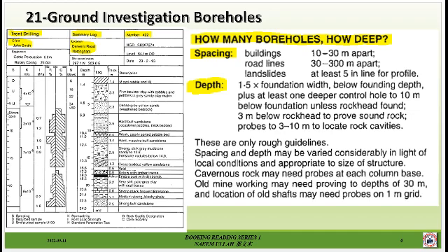Cavernous rock may need probes at each column base. Old mine workings may need proving to depths of 30 meters, and the location of old shafts may need probes on a 1 meter grid.